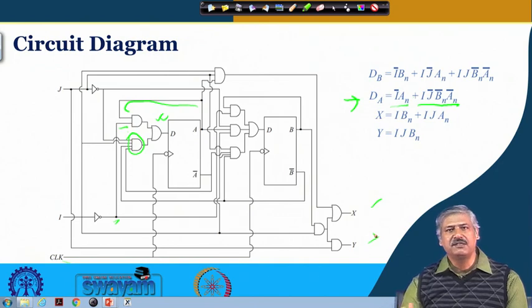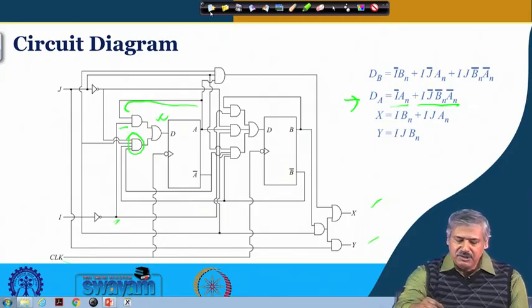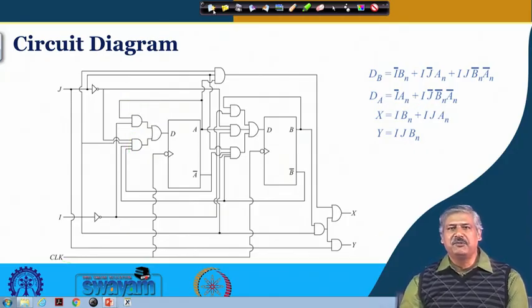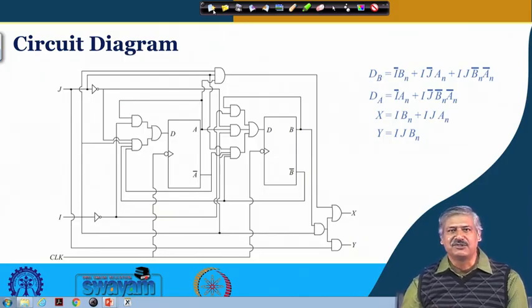Okay. So, you understand how to convert the circuit, we just follow the same steps. Now, note that compared to the JK flip flop based circuit, this looks a little bit more complicated, isn't it? At least the combinatorial circuit part, because it has fewer don't cares, so the equations that you get have more variables, more literals present in the equation.